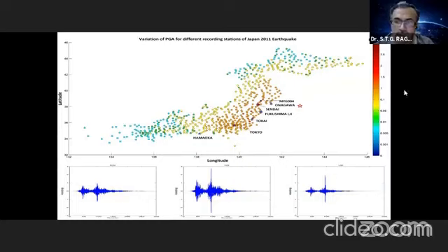Here, if you can see, the maximum PGA reported for this earthquake is something around 3G, the horizontal PGA. This is the epicenter, the star you can see here. At many stations near the epicenter, the peak ground accelerations have exceeded gravity, so the PGAs are more than 1 times G. Now you can compare this number with our IS code.